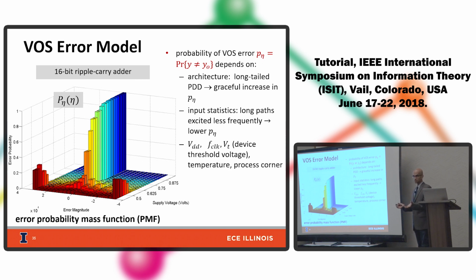So these characterizations you can demand from the circuit designers. Today, circuit designers are only going to work at that clock frequency at which the error has probability 1 of having magnitude 0. We don't want errors. But if we back off from there and create a full characterization of the circuit fabric, then it gives the system designers a lot more flexibility to come up with new design techniques for error compensation.